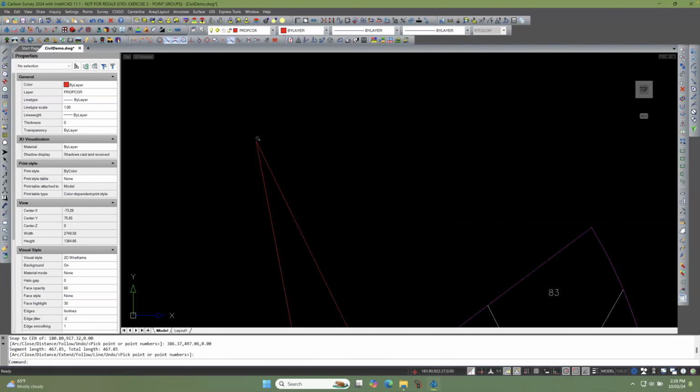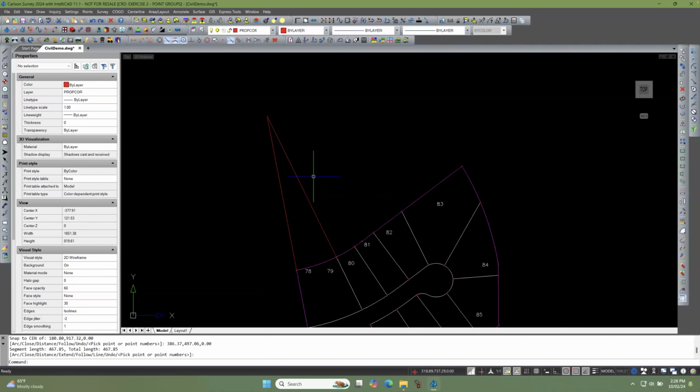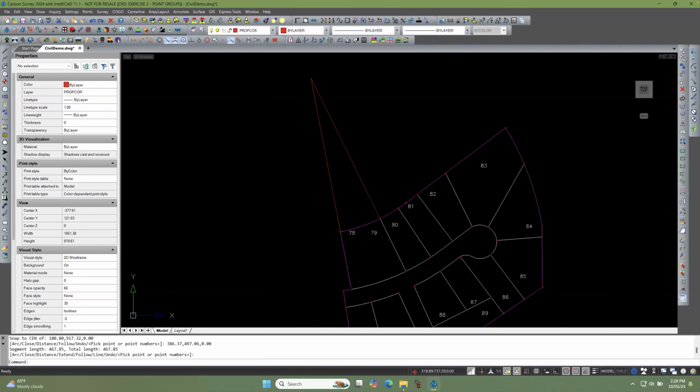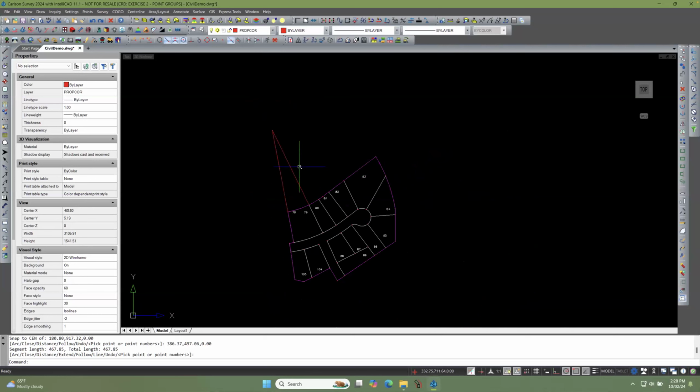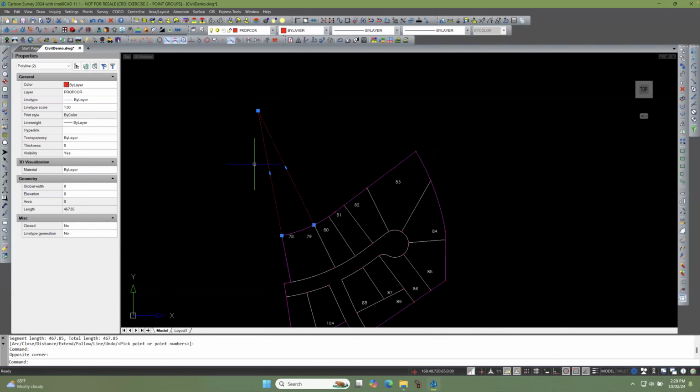And then we're going to go back here and zoom in tight to see if indeed it probably is the very same point. Okay. So they look to be concentric arcs. Now I'm zooming in and out by rolling the wheel on the mouse, by the way. And you can pan the drawing by pressing the wheel in and holding it and moving it back and forth. We didn't go over any of that yet. So I don't have that point way out there. Well, there's no point there other than it is the center of that.